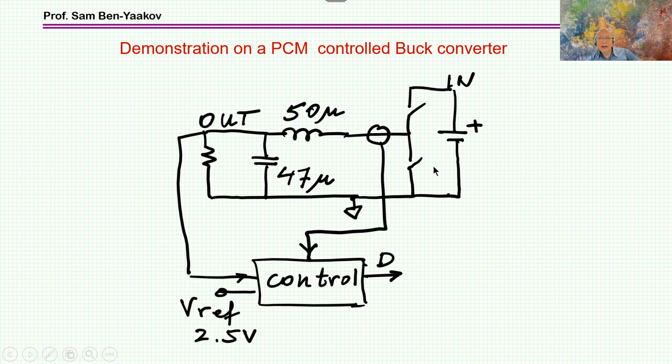I put it on the other side because I wanted also to apply it for the boost, but this is the input. These are the two transistors. I'm measuring the current. This is the control. Here is the inductor, output section, measuring it, everything. All the action of translating all this information into a duty cycle is in here, and it is the Middlebrook equation. That's what's in here, because it needs all this information, okay?